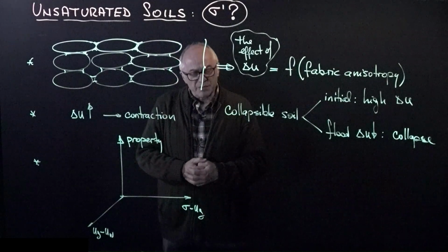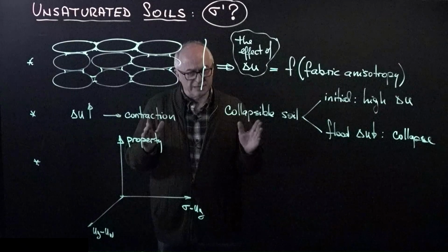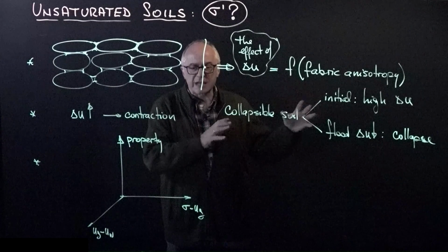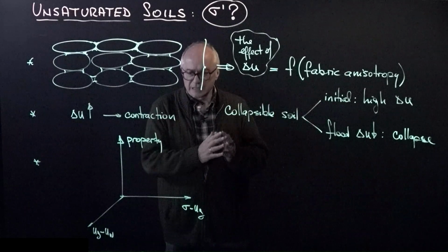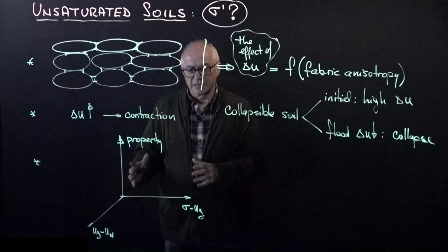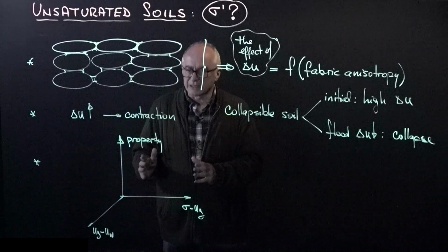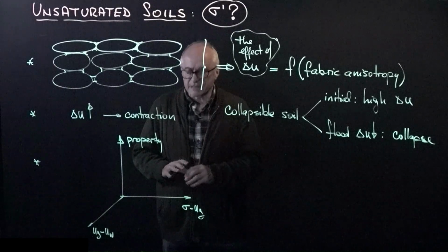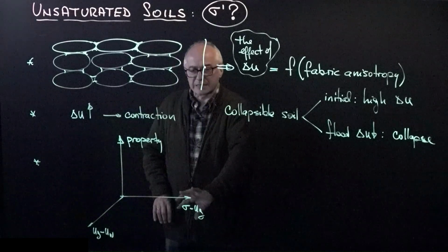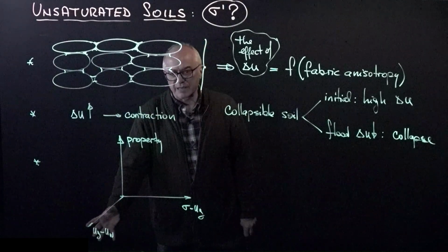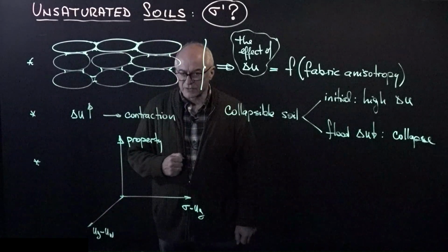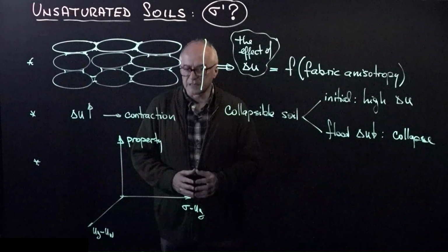So indeed, we have to explore in every case whether the simplified and convenient formulation of merging suction with Terzaghi's effective stress is sufficient, or we actually need a little bit more complex but more versatile and physically correct approach in which we separate these two causal mechanisms, one that is happening at the boundary and one that is taking place locally, in order to properly anticipate the behavior of our soils and the performance of our engineering systems.